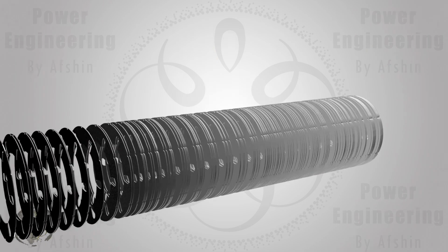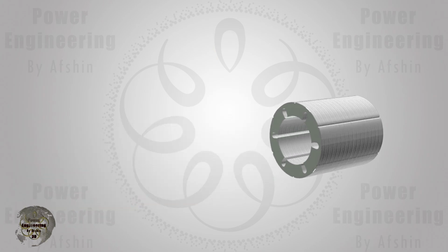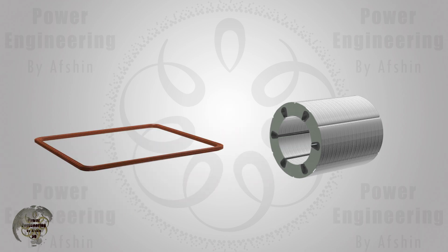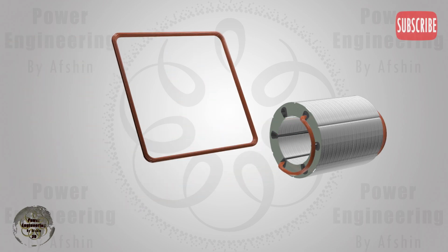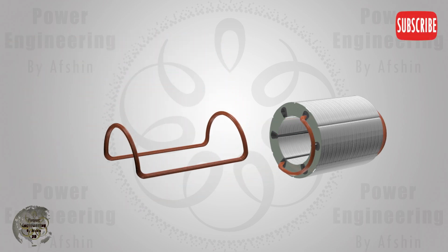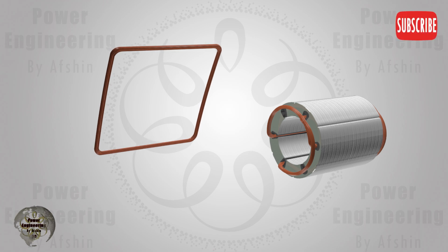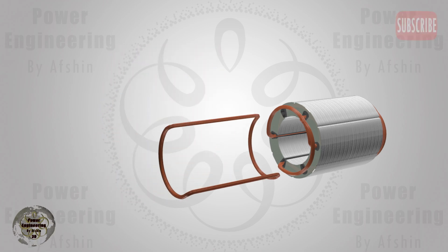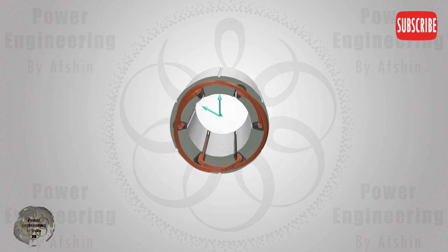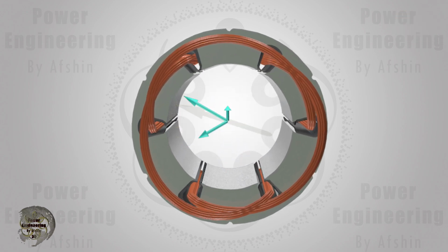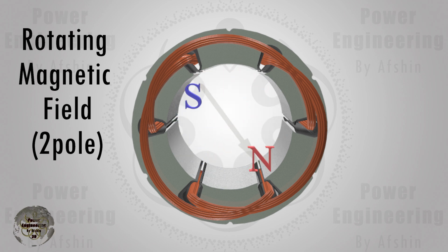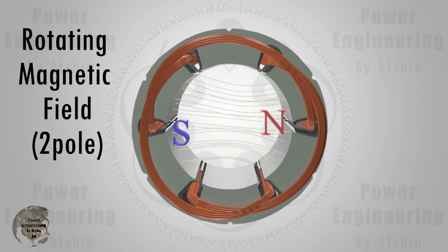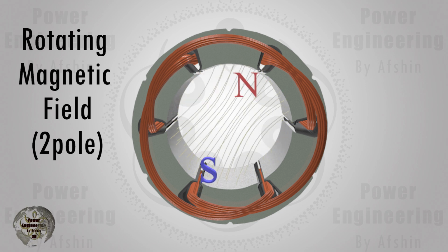Consider an induction motor stator with only 6 slots and 3 coils. While real stators typically have more slots and coils, we've chosen 6 slots and 3 coils to avoid complexity. When three-phase voltage is connected to the stator, a rotating magnetic field with constant amplitude is generated inside the motor. Additionally, the magnetic flux lines for a bipolar motor follow a similar pattern.